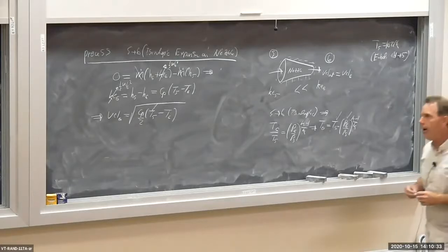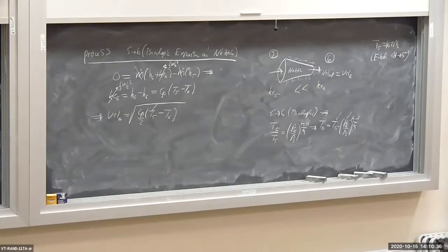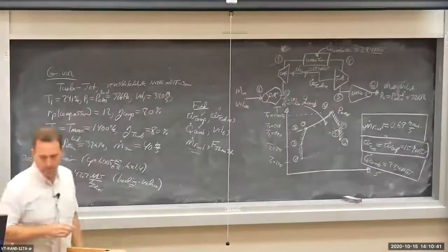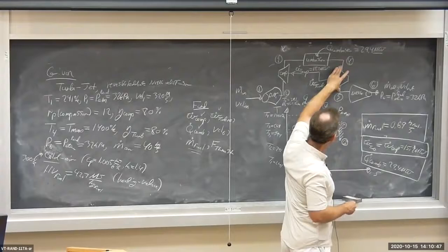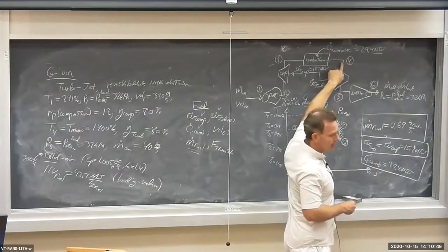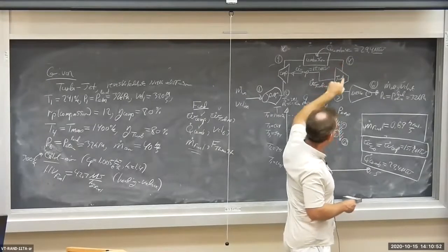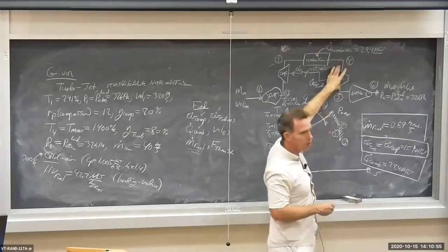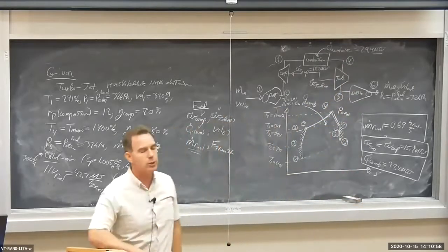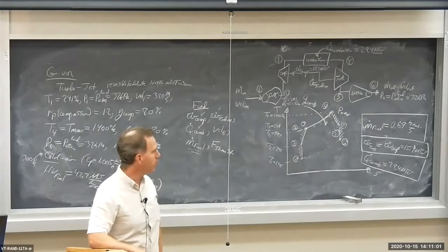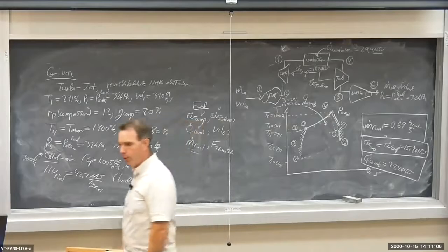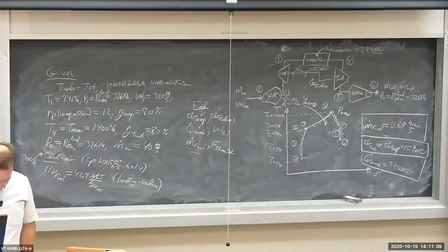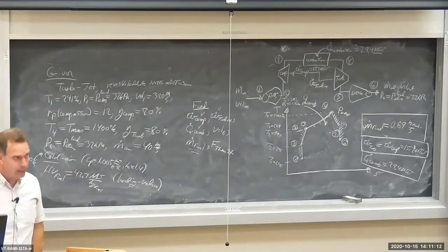Well, I could apply the isentropic property relationship to the turbine. If I know the pressure in the combustor, and I know the temperature drop across the turbine, I can use a property relationship to get the pressure drop from the temperature drop and get P5. So I'm not going to go through the details here, but P5, let's see if I have it here. P5 is 197 kilopascals.